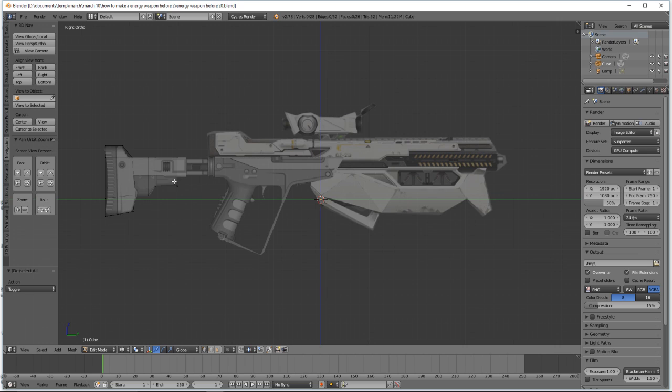Okay, if you look here, you can see we need to extrude from here, but see right here, there's no loop cut. So we need a loop cut right here. So we're going to hold control. Then while we hold control, we're going to press R. I'm then going to left click once to put that loop cut in. Because I only left click one time, I can move this loop cut. I'm going to move this down like this. Moving it some more. I'm then going to left click a second time to totally lock that loop cut in.